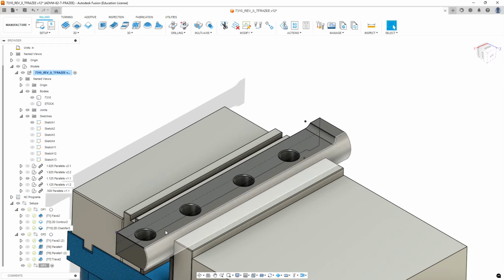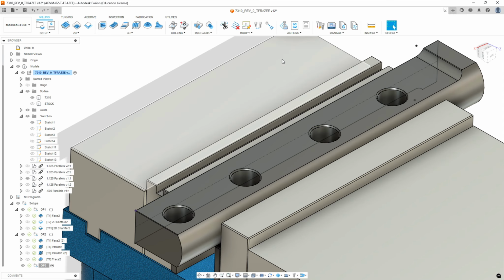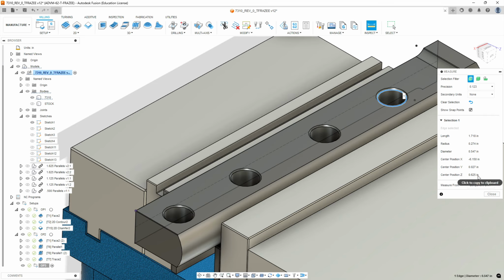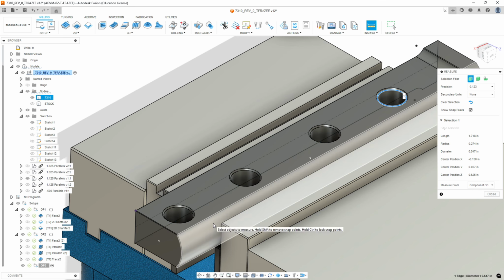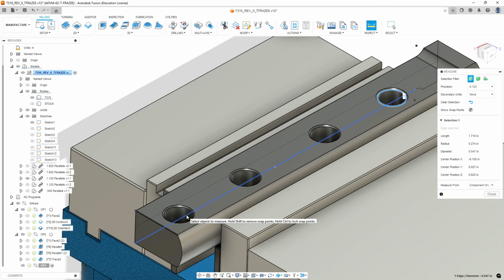And what we're going to do here is we're going to machine these holes. Okay. And I do believe we have a 1/2 inch drill bit in our library. And if we check this hole diameter, it is 547 thousandths, so it's bigger than a 1/2 inch. So there's a couple approaches we could take. We could just circle and interpolate these, don't worry about a drill bit, and pocket them. And then the other approach is we rough them with a 1/2 inch drill bit, and then we come back and do a contour with a smaller cutter.